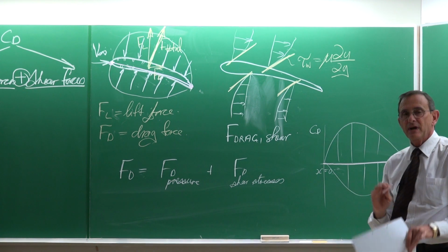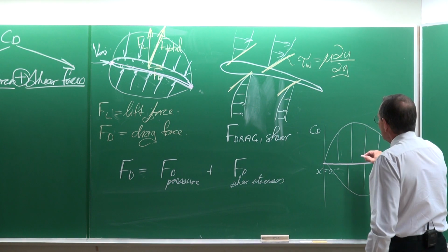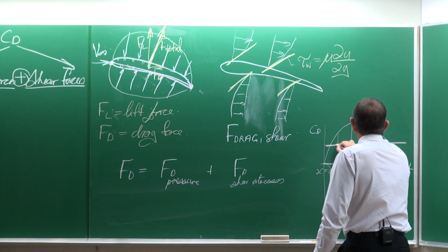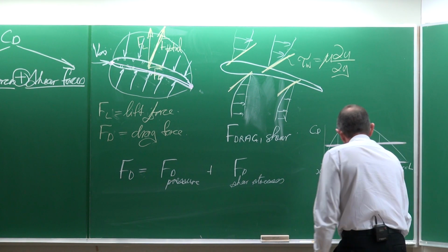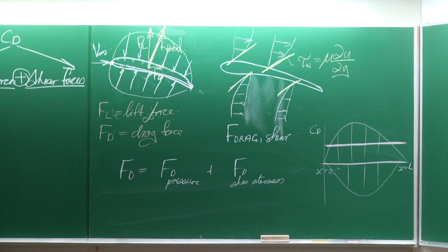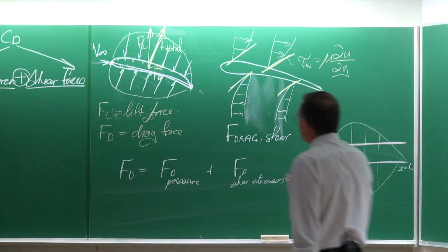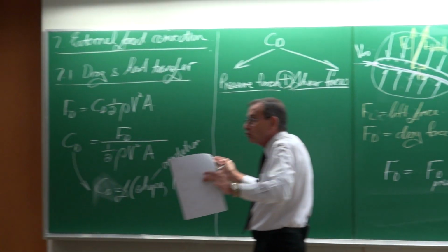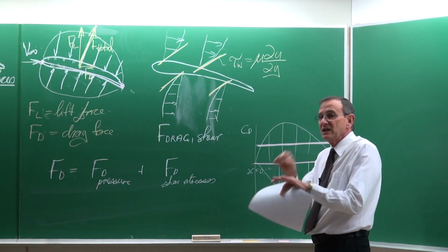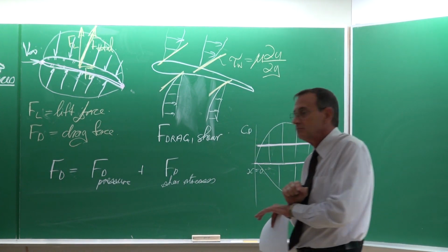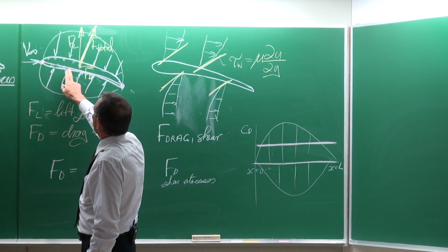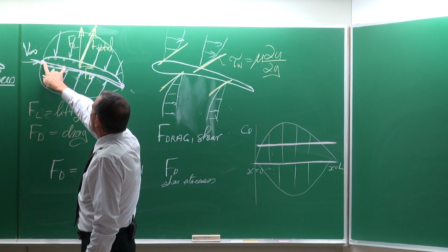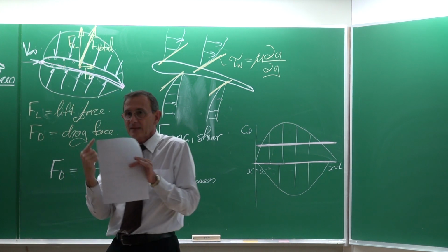And because we have done all the mathematics, you're going to integrate it so that you can determine the average. And as engineers, in many cases, we are interested in getting the average. So this drag coefficient can include the total body, or it can be determined at a very specific point. For example, maybe a quarter of the chord, you can determine it at that specific point.